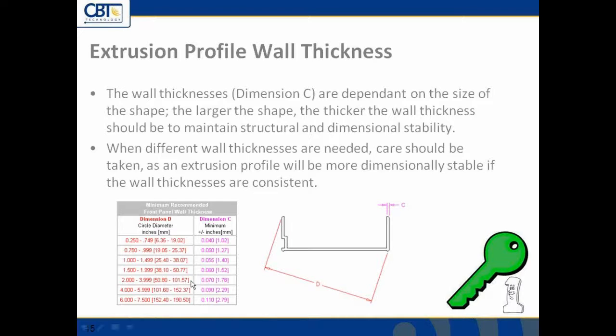And we're going to be working with you to try and get those numbers in this range here. Again, not set in stone, sort of a rule of thumb, but we're going to be looking at 80 thousandths, 90 thousandths, maybe even 100 thousandths in cases like that in order for the extrusion process to work properly. So good thing to keep in mind there too.